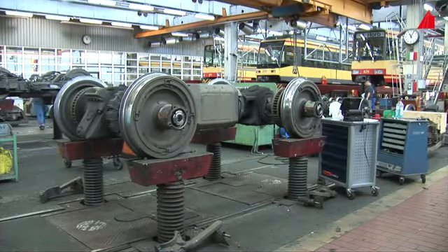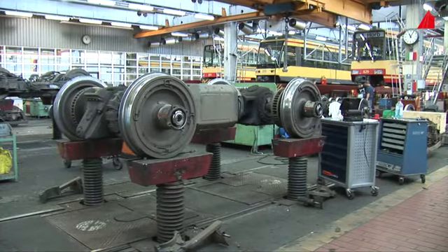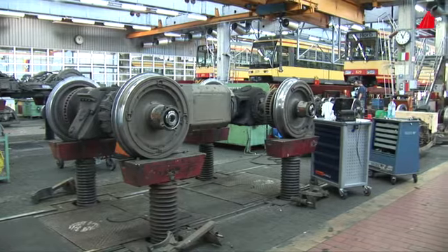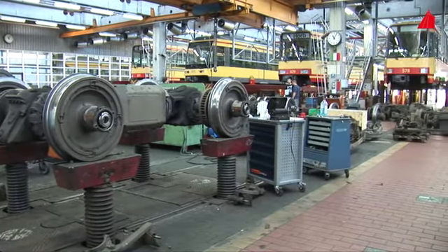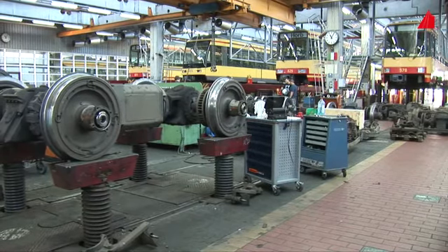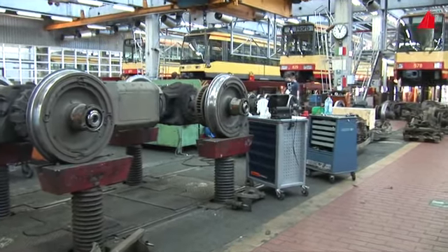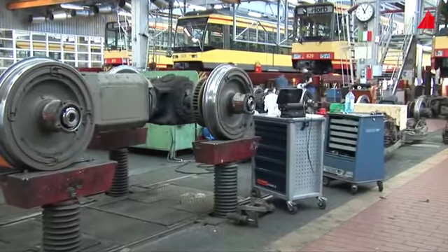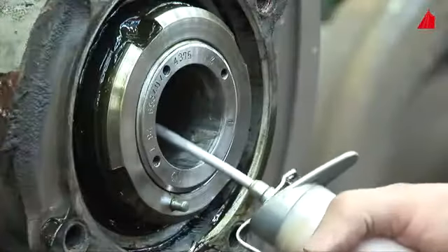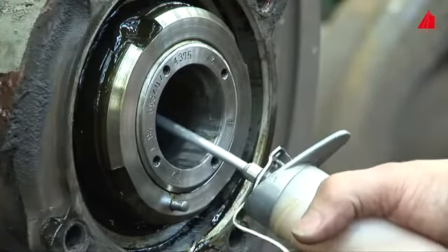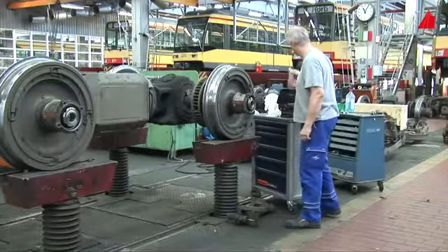This is one of the bogies, jacked up to comfortable working height and prepared for ultrasonic inspection. Special attention is given to the wheel axle, among experts known as wheel set axle. It has been designed as a hollow axle. This saves weight and facilitates the ultrasonic examination. The material tester applies a suitable oil as a couplant into the bore of the axle.